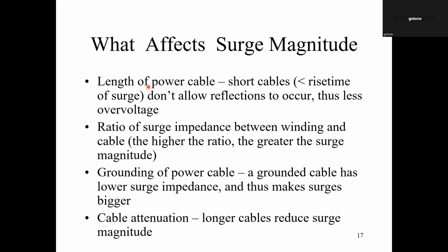And in fact, most cabling, even for low voltage motors, is usually shielded in some way for electromagnetic interference reasons. Okay, so this is always something that can affect things, and it makes things worse. Also, there's the fact that there's attenuation. As impulses travel on a cable, there will be an impact on the magnitude of those pulses, as the losses in that cable suck away some of that energy.